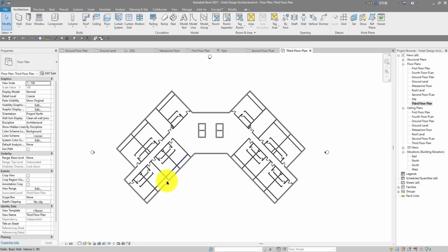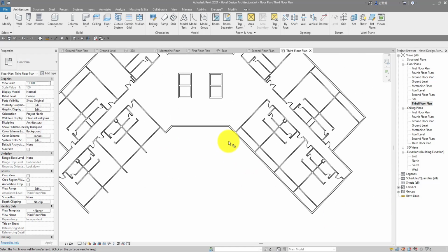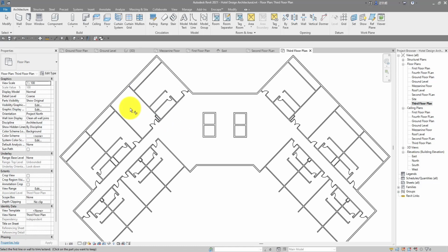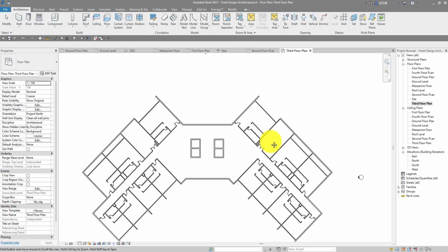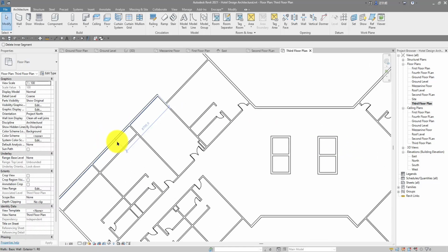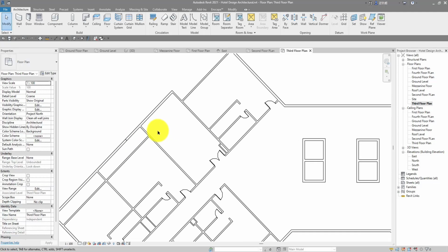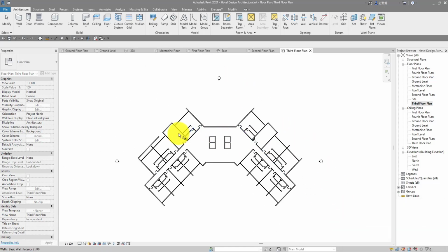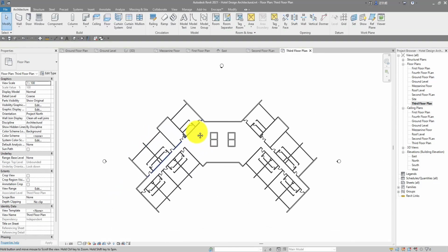Going back into the third, the same thing. TR, trim this to this, hit on join. TR, this to this, on join. We are still in that command, so we can just trim this to this and just trim this to this as well. And then we would want to split that wall. Or what we can also do, guys, is just the same TR. You can just hit the same TR, and then on join that over there. All right, I totally forgot I had that shortcut.